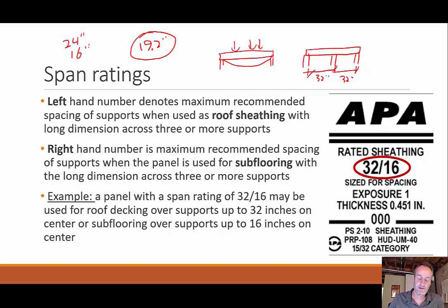That's 19.2. So here's a piece of trivia for you if you have a decent tape measure. All right, so what I have is a basic tape measure, and if I scroll it out to 19.2, I can see that there's a little triangle right there showing me that's where my spacing would be. Should be another one, 38.4. I can see another little triangle right there. And that'll keep going all the way through your 8 feet so you get your spacing. So 19.2 is one of those that not as many people are familiar with, but a little trivia for you. Next time you get a tape measure, ask someone else what that little triangle is for at 19.2.